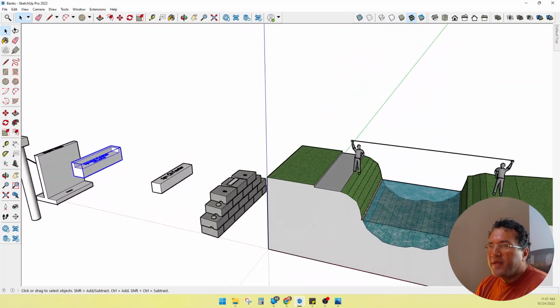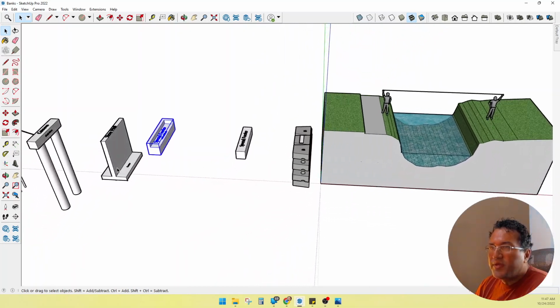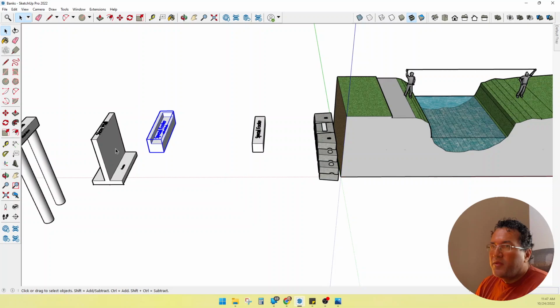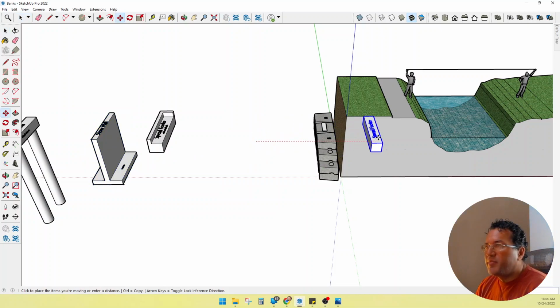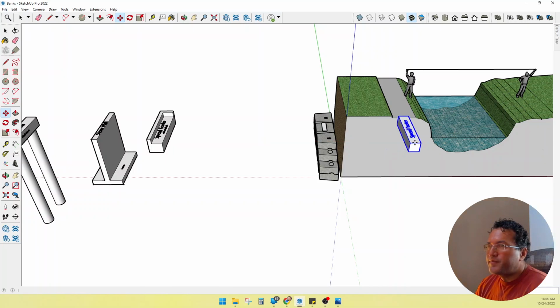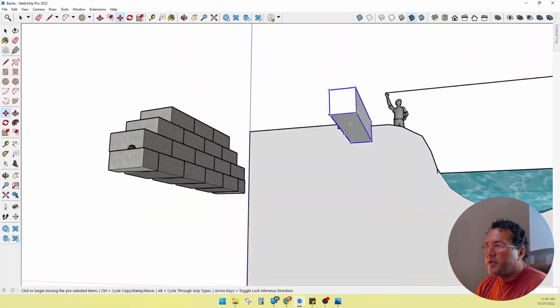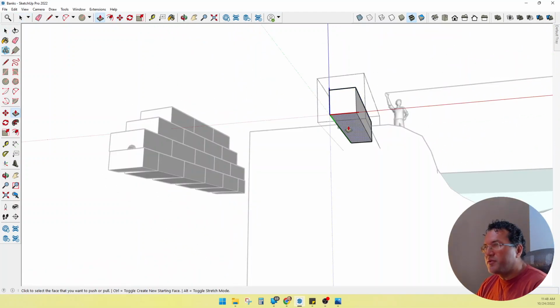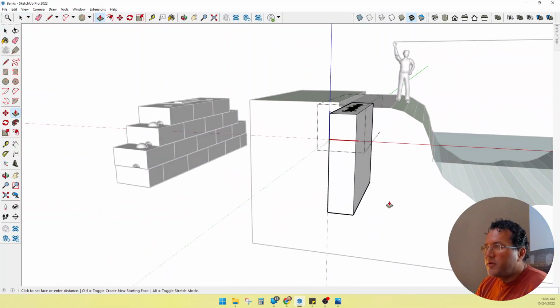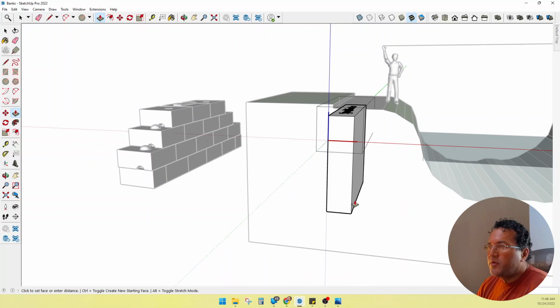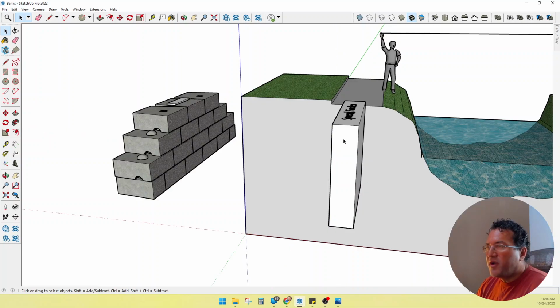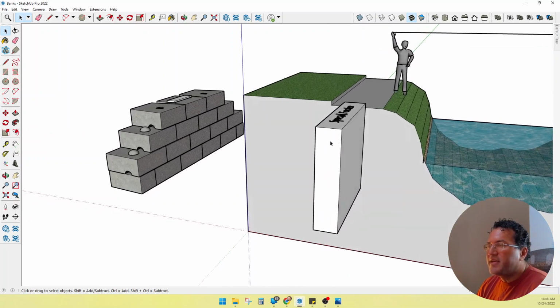And the next, so now your cost starts jumping way up. And the reason why we start having to go to this abutment style is, actually, I'm going to go back to this one. Sometimes whenever you're building this kind of abutment, and now that's 24 inches wide, let's say your soils are really poor, so now you're having to make your abutment super deep in order to either get below the waterway or get below your poor soils in order to get to good soils. You're going really deep, and that amount of concrete can be very expensive. That's a ton of concrete there.